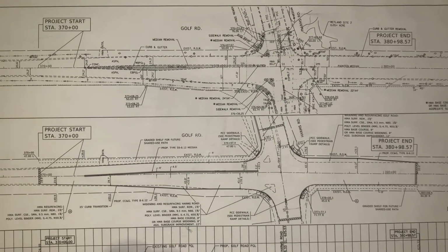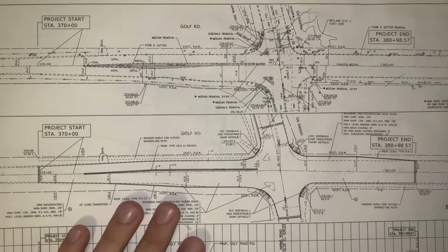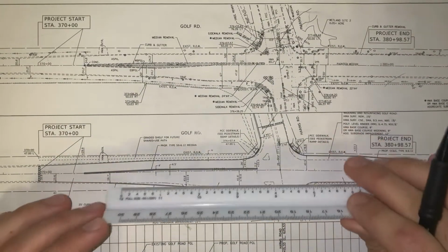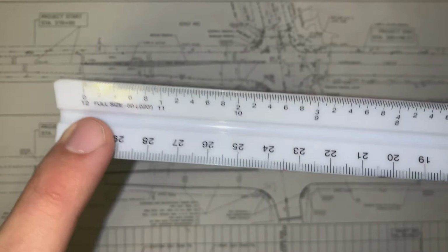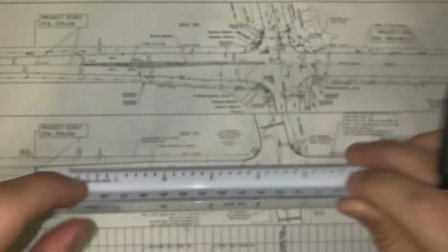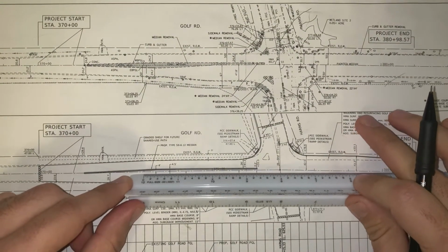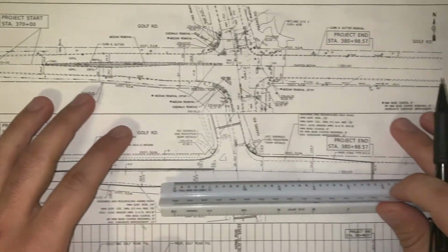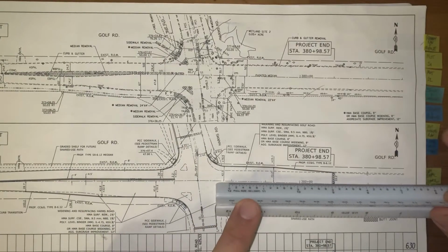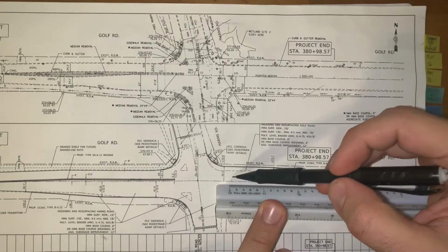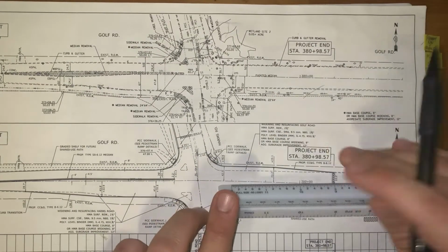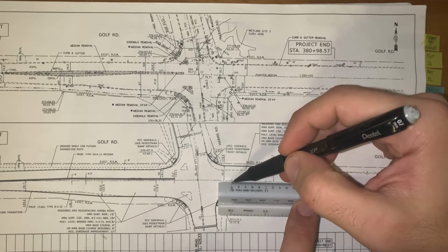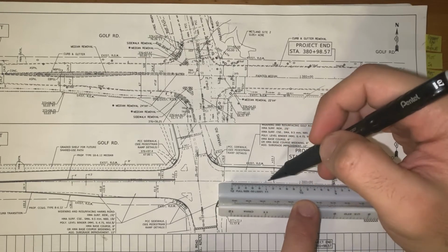In our specific case, this is an 11 by 17 drawing, so it's easy to put your scale to the full size. You can see the 100-foot tick marks, and it's probably easier to show it here on a clear section. The 100-foot tick marks shown here will line up exactly with the 0 to 1 shown on the scale.